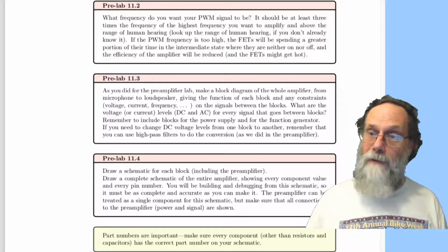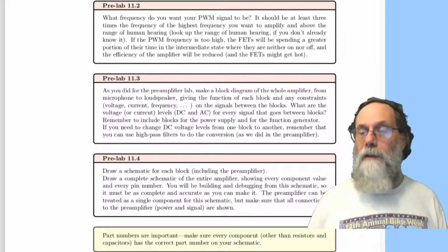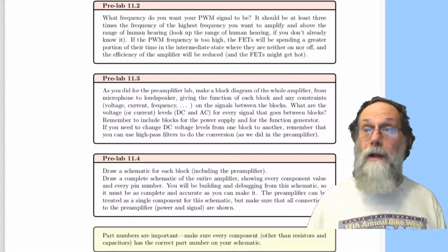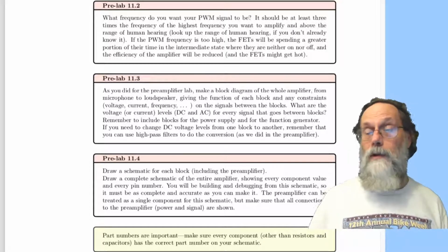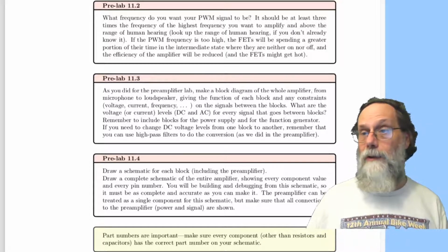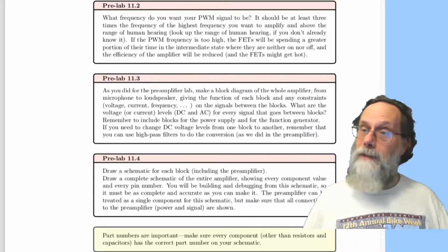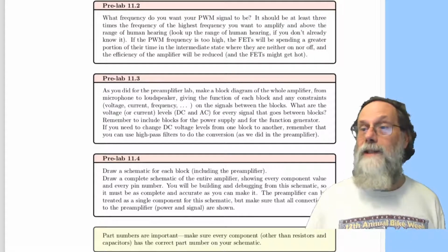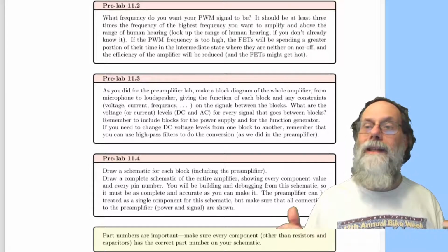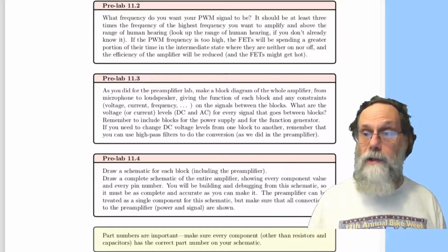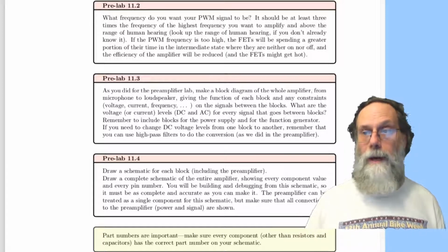That's one of the reasons for having the signal levels and stuff all very explicit there, so you can see, oh, there's an incompatibility here. This is assuming it's got an input centered at 2.5 volts. This thing's got an output centered at 1.65 volts. Inconsistent. Make sure that everything is consistent, and you can tell the consistency just from the block diagram.